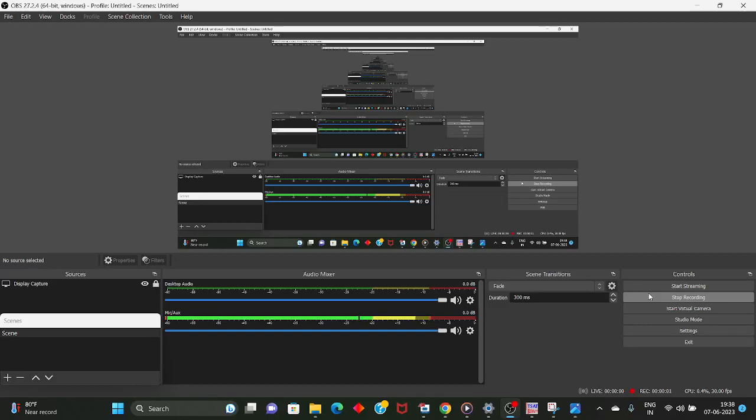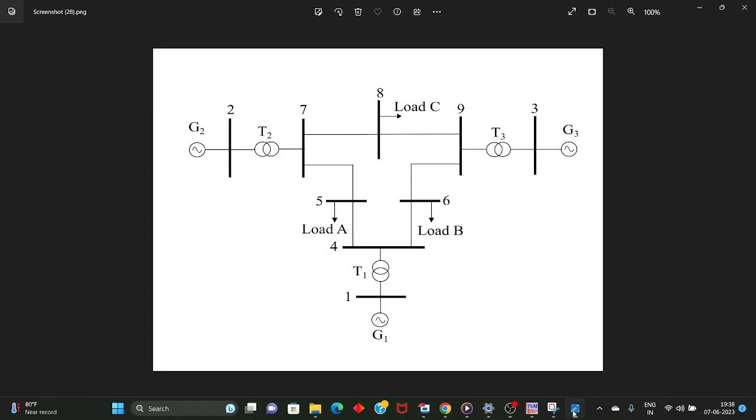Hello everyone, in this video we will check how to configure ePMU on the TSAT module of DSA Tools software. So we will start with a test system. We will be emulating PMUs on this test system. This is the IEEE 9 bus system. Let us see how we can add three PMUs at the generator buses, like bus number 1, 2 and 3.